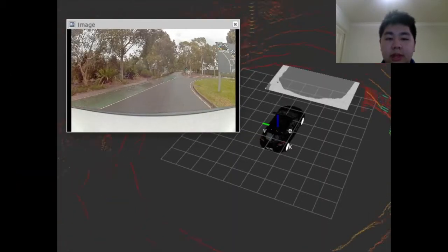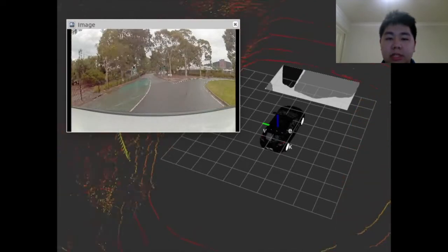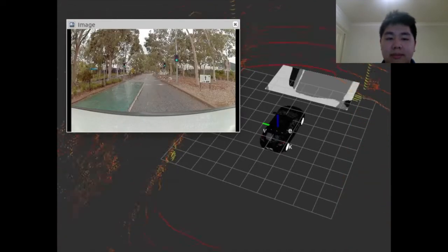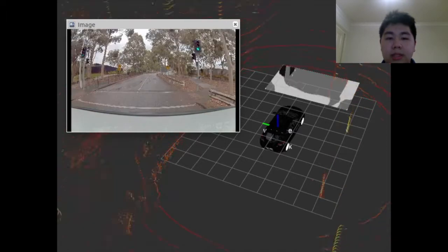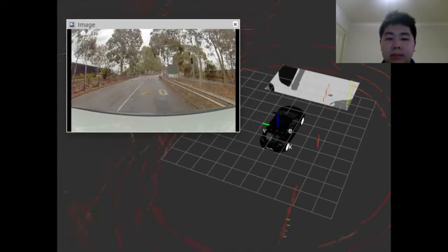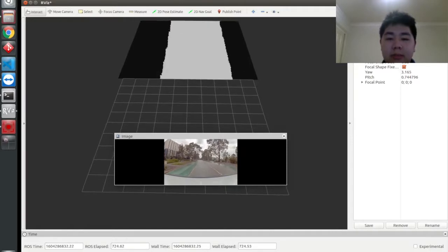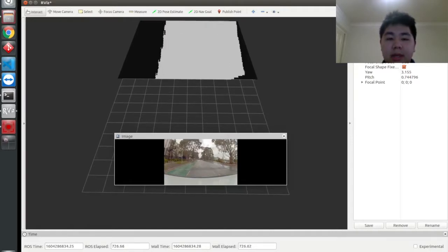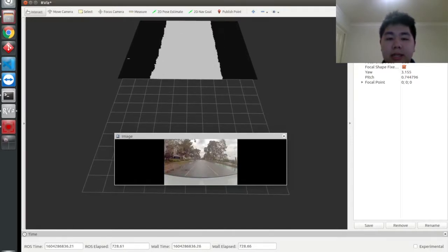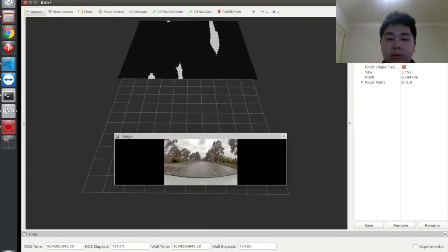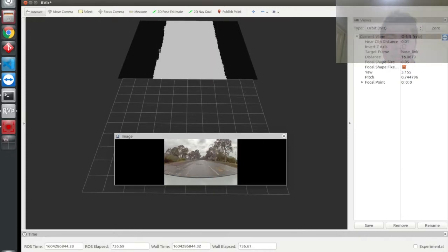The results from the drivable lane detection system were utilized by other key projects MCAV have been working on. One particular use of our lane detection system is that it provides information to our path planning system by transforming the output detection to a cost map. This also involved taking the output detection and projecting it to 3D space, which then allows paths to be dynamically planned without requiring predefined boundaries.